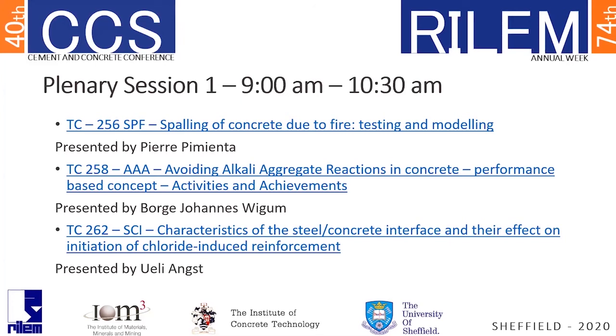And in that condition, there may be an overall effect of pH, but there is no literature, or very limited literature data, looking at the pH in a steel-concrete interface system rather than a steel-solution system. And of course, different cements may lead to different pHs, but there are other influencing factors coming from the cement. For instance, they may lead to different microstructure, pore structure at the steel-concrete interface.